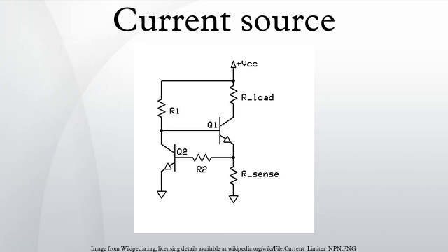The load can be connected either in the emitter or in the collector, but in both cases it is floating as in all the circuits above. The transistor is not needed if the required current doesn't exceed the sourcing ability of the op-amp. The article on current mirror discusses another example of these so-called gain-boosted current mirrors.